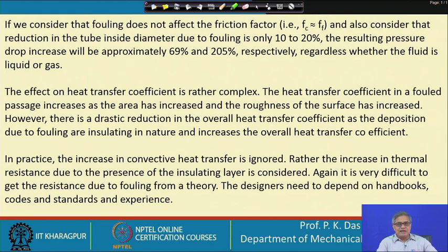So, if there is any kind of control strategy, let us say a cleaning strategy, that will keep the heat transfer passages clean, that cannot be only once, that cannot be only twice. At regular intervals we have to have some sort of cleaning of these passages.